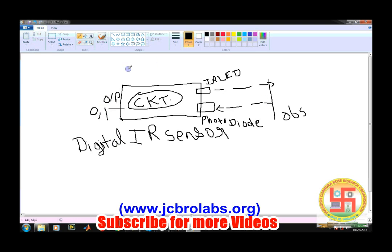I am repeating again: in the IR sensor there is a PCB circuit, and the IR LED is emitting light. If there is no obstacle, there will be no IR radiation coming back to the photodiode. As soon as there is an obstacle, this radiation will come back to the photodiode, and then the output will become 1.